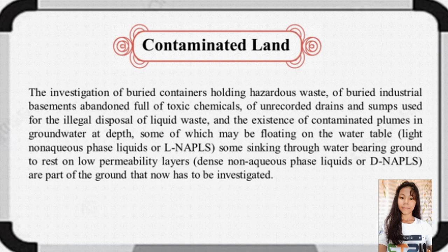Contaminated land. The investigation of buried containers holding hazardous waste, of buried industrial basements abandoned, full of toxic chemicals, of unrecorded drains and sumps used for the illegal disposal of liquid waste, and the existence of contaminated plumes in groundwater at depth, some of which may be floating on the water table, the light non-aqueous phase liquids or LNAPLs, some sinking through water-bearing ground to rest on low permeability layers, dense non-aqueous phase liquids or DNAPLs, are part of the ground that now has to be investigated.